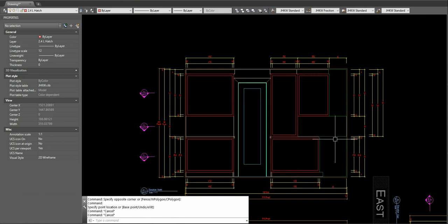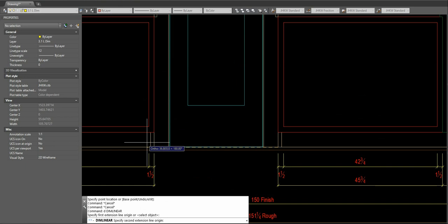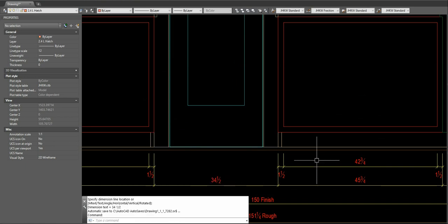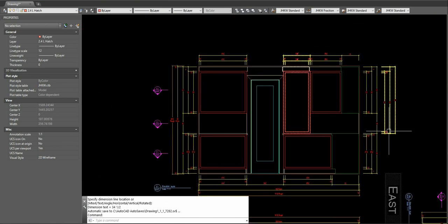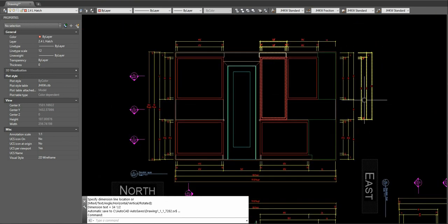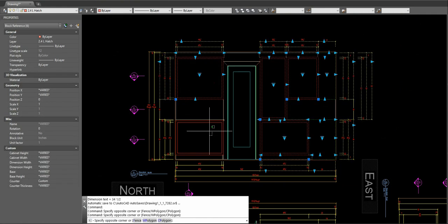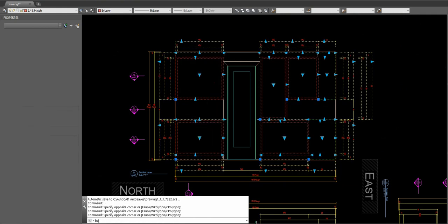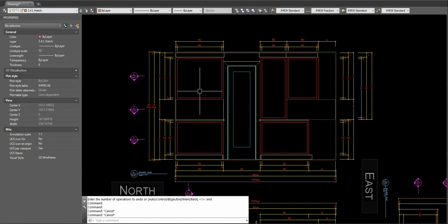Yeah, shoot, these are all dynamic blocks. They have dimensions added to them. This is still just plain old 2D AutoCAD, so whatever dimensions I need to add to complete this string, you can do that. I am going to select these blocks and burst them so that they are now just closed polylines on a faced frame layer.